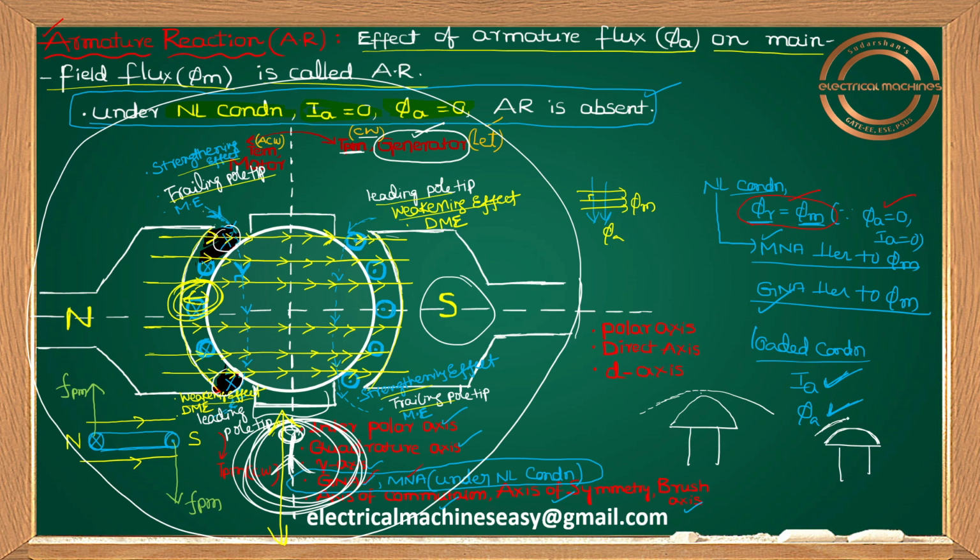If you observe clearly, under the pole shoe the air gap is uniform. I think it is very clearly visible, right? So the air gap under your pole shoe is the same for non-chamfered poles. But for chamfered poles, if you observe clearly, along the pole center,